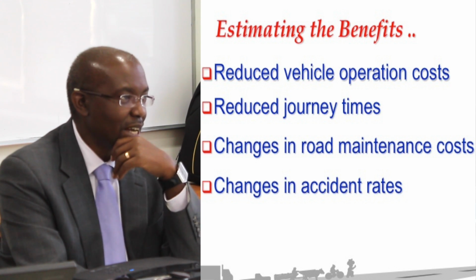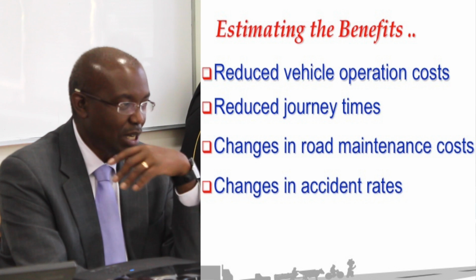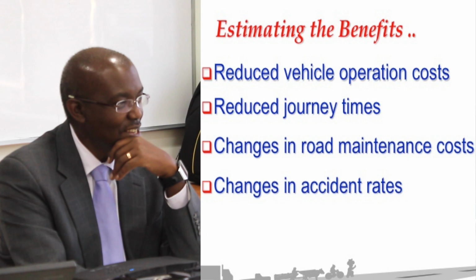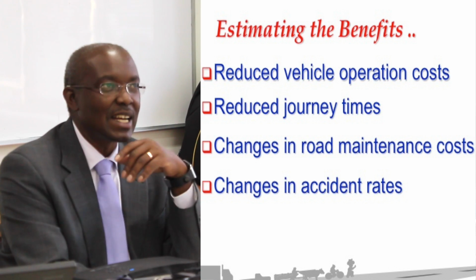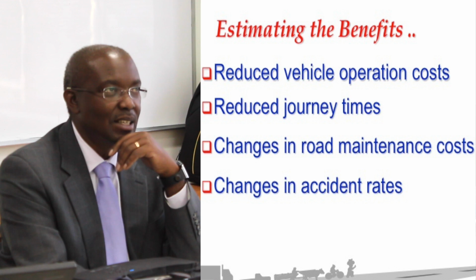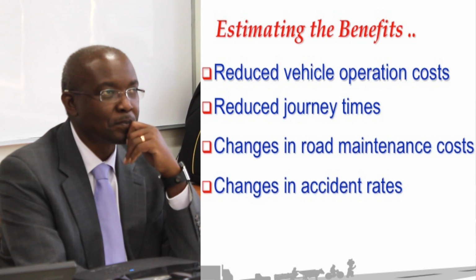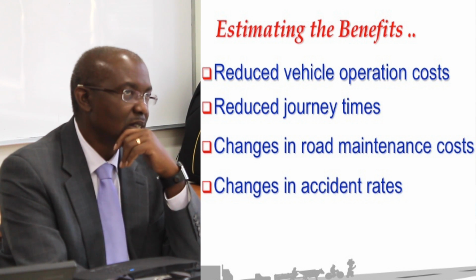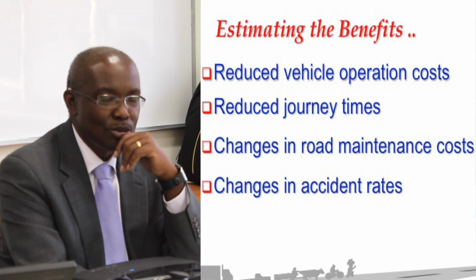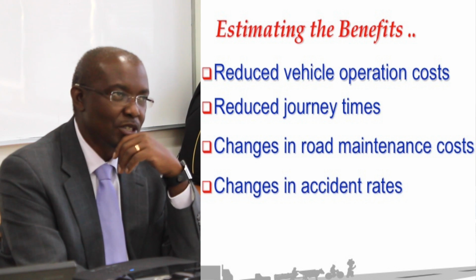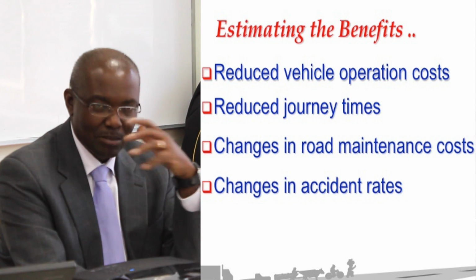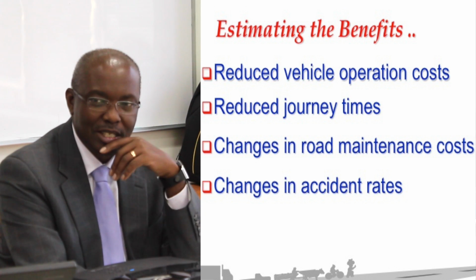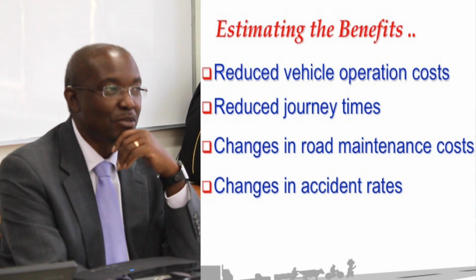What is the value of time of the average passenger? And how many of those passengers are there? Okay? In a year. Okay, so that adds to the benefits from travel time savings. Then you have changes in road maintenance costs, which usually, depending on what you do, if you're widening the road, the first 10 years the maintenance costs may be low, but after that it may be higher. But because you're discounting, it will still come up as a benefit.